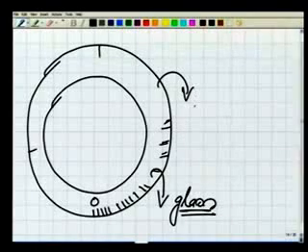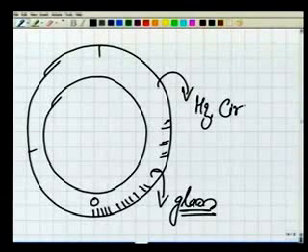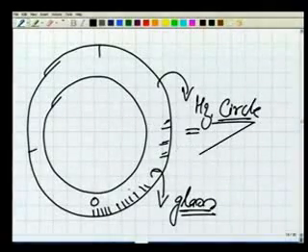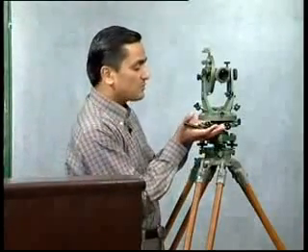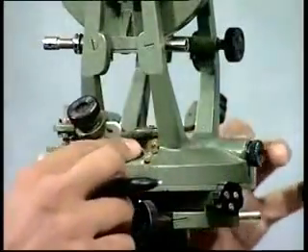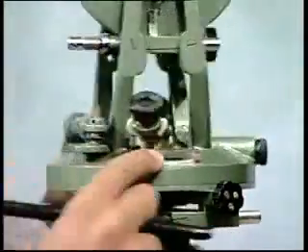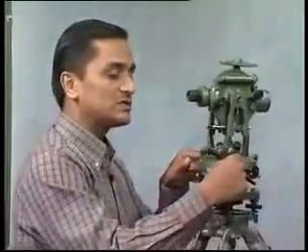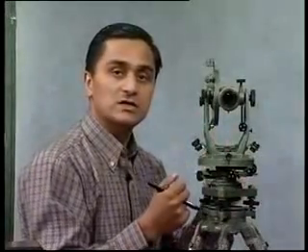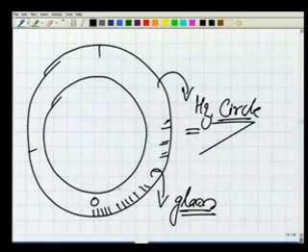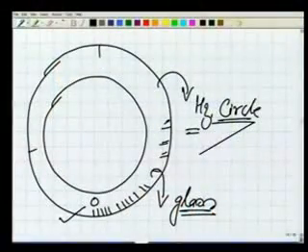So this is called the horizontal circle, and we make use of this for measuring the horizontal angles, as we will see in a moment. Now further on top of the horizontal circle or horizontal plate, we cannot see right now, but we have 2 windows here, one little window here and one little window on this side. Now these 2 windows are basically to see the readings, because as I was saying, we have the horizontal circle here. We need to read the angle values in this horizontal circle or this graduated circle.